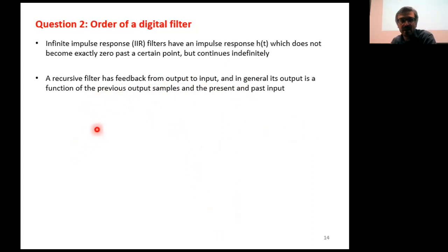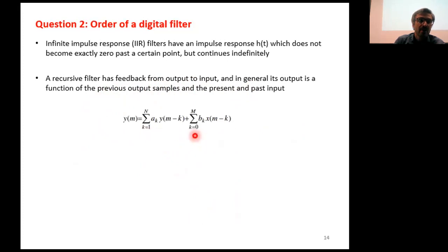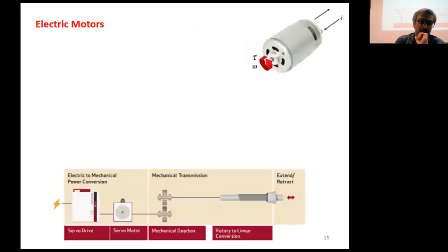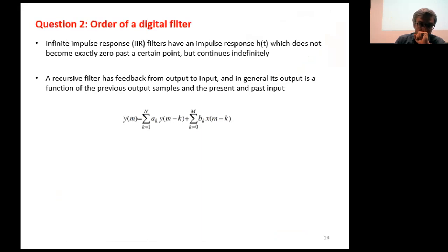As in the previous case, the example you saw was like this kind of filter. And as this kind of finite difference equation, you see here that we not only have the inputs but also the outputs in the difference equation. So in this case, you need to work out the transfer function and see the denominator to check the filter. But in general, it's the number of oldest samples, either in input or output, that is in the difference equation that tells you what is the order of the filter. Is it clear? Everything's clear? This was just a question from yesterday.